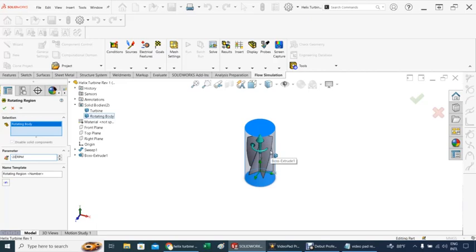So, for example, if I put a huge number here, 2000, let's say 2000 RPM, what will happen? Well, the question is, will the wind sustain the 2000 RPM clockwise? Probably not. And you will have a torque that will indicate that for you to spin this blade at 2000 RPM, you have to spend energy into it.